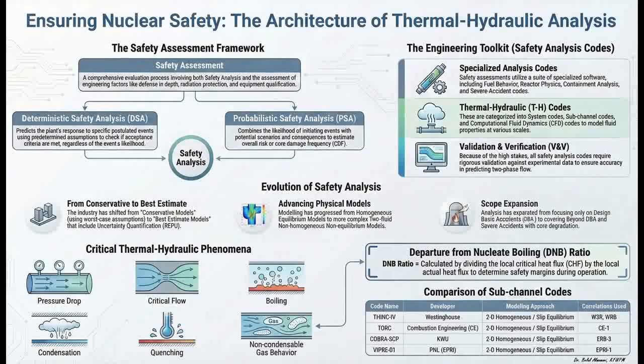And even if we could resolve the scaling issues and eliminate data scatter, there's an inescapable structural limitation inherent to the software itself. The slides identify it as representation uncertainty or nodalization. Yes, translating a physical 3D power plant into discrete digital blocks or nodes for a computer to read will always introduce a gap between the code and physical reality. If your nodes are too large, the mathematical average completely glosses over highly localized physical phenomena, like a localized temperature spike on a single grid spacer.